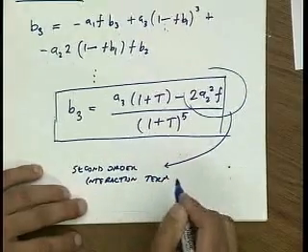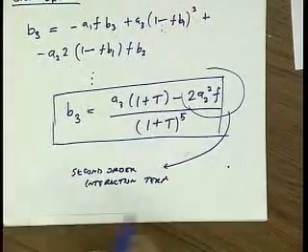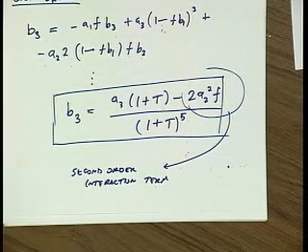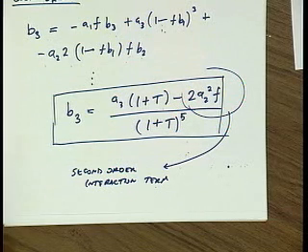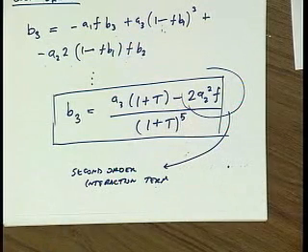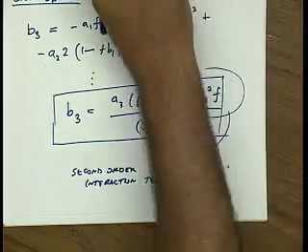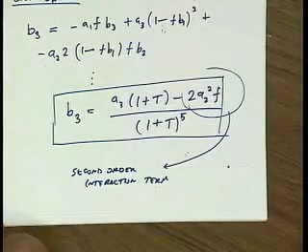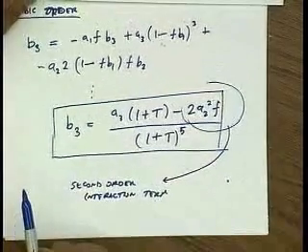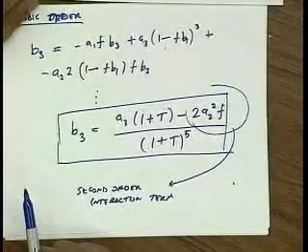Remember last lecture we talked about a FET, and we said ideally a long channel FET has no cubic. But if there's any kind of feedback in that FET, for instance, source resistance, shunt feedback through that Miller capacitor, if there's any kind of feedback, which in reality there's going to be, then second order interaction will generate cubic distortion. Okay? So where does cubic distortion come from? Okay, anybody? How do we get cubic from second order in a feedback system? Anybody want to venture a guess?